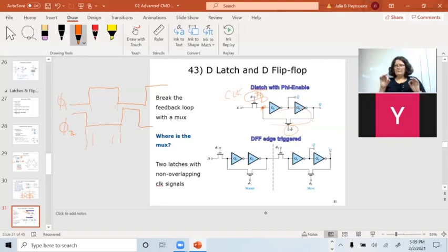I have to make both clocks out of one clock. So there are little delay tricks and things like that, that's all inside the part of the flip-flop that Bruce does. Okay. So what I want here, when phi 1 is true, this transistor goes on.